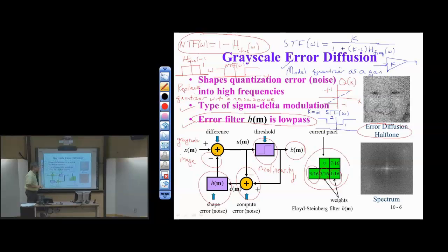So that's our signal transfer function. It passes all frequencies, and you'll note that the higher frequencies are amplified. So low frequencies, all pass response, no change in amplitude. Higher frequencies are amplified. This is the sharpening effect, that the high frequencies get amplified, which results in a sharpened image.